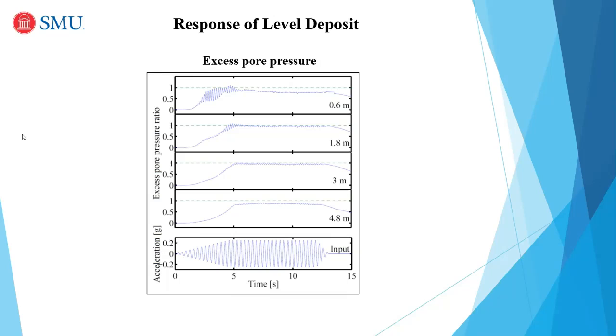Of course, anything that is supported on that soil will sink, collapse, and significant lateral deformation can happen if there is even a mild slope. So it's a very dangerous phenomenon. Usually it takes place in high seismic areas and, of course, in saturated loose sand that is near the surface. So with this simple definition, here is the input motion at the base,